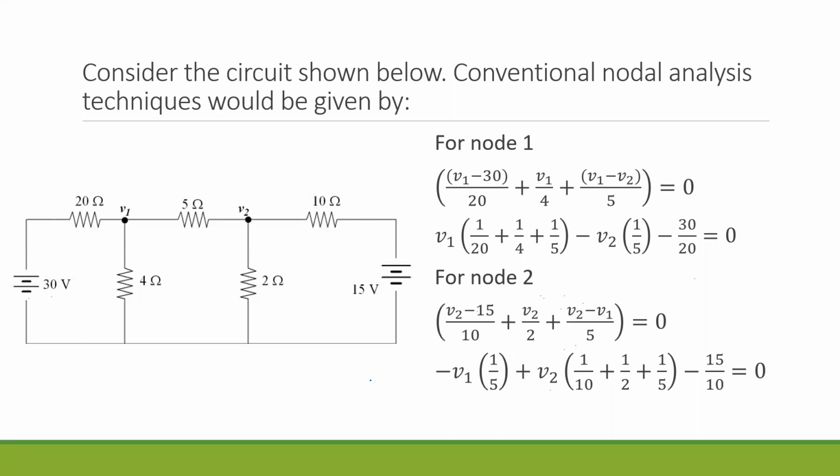All right. So A11, as we said, would be the sum of the reciprocals of each of those elements, which would be that. Next, we have 2 nodes, so what size matrix would we be dealing with? 2 by 2. Good. What's the element between nodes 1 and 2? The 5 ohm.